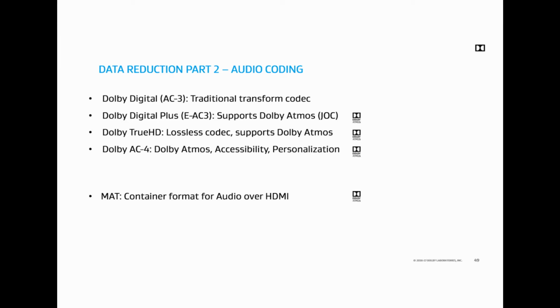I've also put on the slide another technology, and another challenge that we came across was it was one thing to get a more immersive audio into the home, but then how do you get it from your TV or your set-top box, cable box, to an audio-visual receiver or a soundbar? And so regular HDMI is great at carrying PCM. So we had to come up with a format to pack decoded PCM with object metadata so that it could flow over HDMI pipes in the home. And that's what that last MAT technology is about.